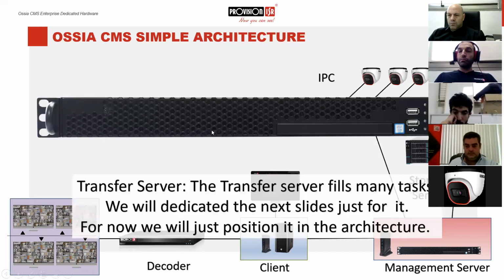Tal, sorry, one more question. If you want me to keep it to the end, we can keep it to the end. But with the 4 monitors that you put there, the resolution, because once you watch over 8 cameras at a time, the resolution drops. Will it be the same here? Yeah, it works very similar to an NVR. Later in the presentation, there is a technical spec of the decoder together with the decoding capabilities. What's the resolution for 1 channel, 4 channel, 9 channel, 16 channel, and so on. But like you said, of course, there is no reason to show 36 channels in mainstream, meaning 4 or 5 megapixel, because anyway, it's very small on the screen. So we go down to substream.